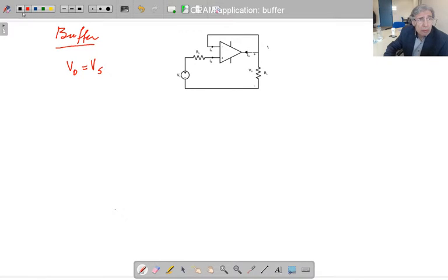So immediately you are going to say that if this is equal, you've got to connect a short circuit here, and this becomes equal. Why do you need all these elements? Let me finish it and then answer that question. Well, definitely we need the definition relation of this ideal operational amplifier. Just to remind you, Vp minus Vn is almost 0, and Ip equals In is almost 0.